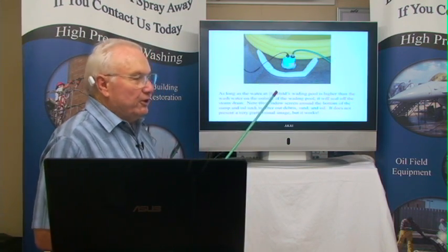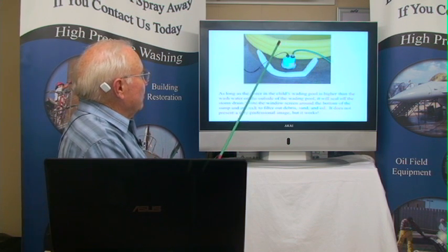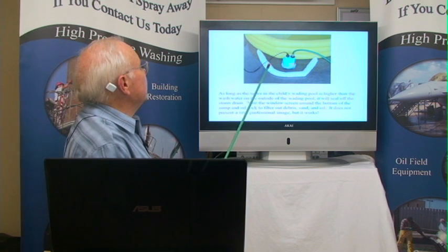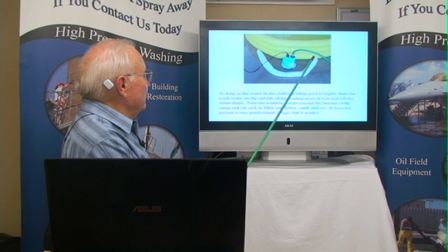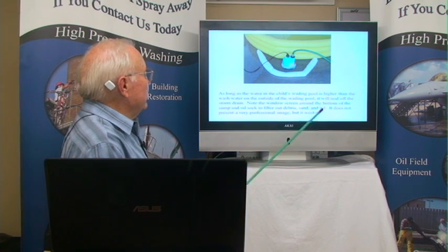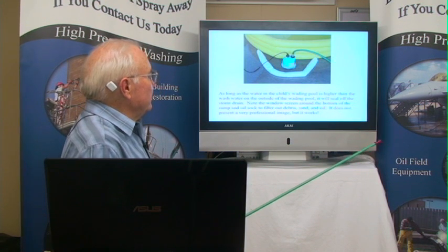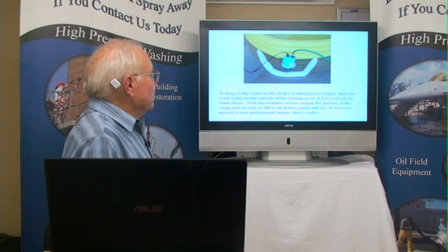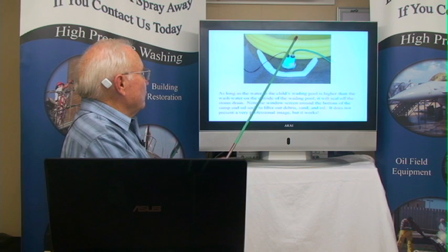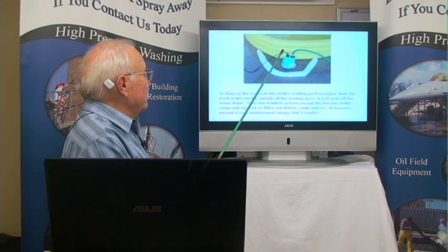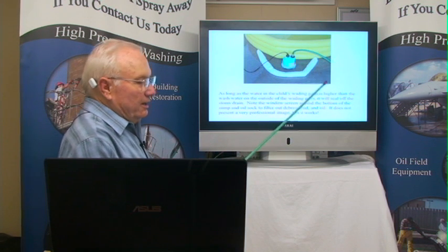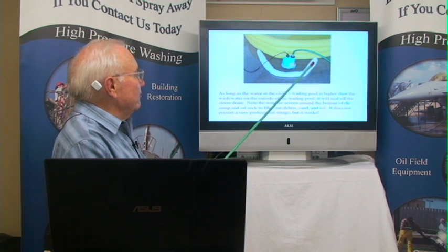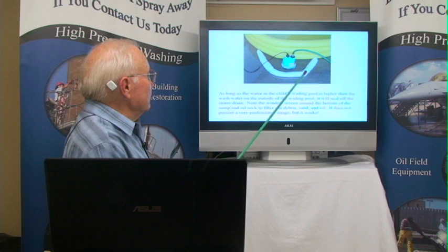I thought this was pretty unique. Contractor went out and bought a child's wading pool. He got a sump pump from Home Depot. He put an absorbent boom around it and a screen down in the bottom. So he did his pre-cleaning with a leaf blower, and as long as the water is higher on the inside of this child's wading pool than it is on the outside, that'll seal off a storm drain real good. Doesn't look professional, but it works.